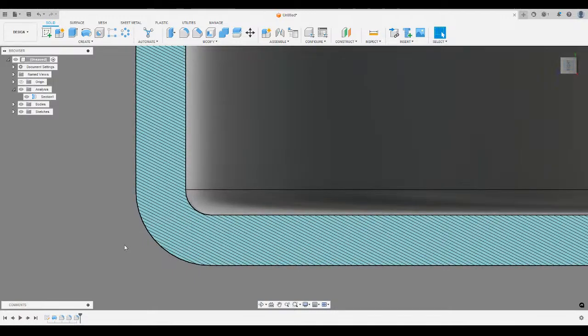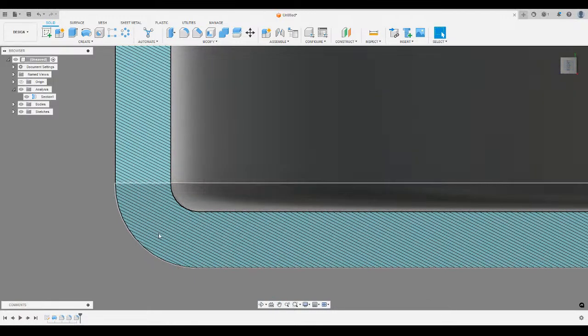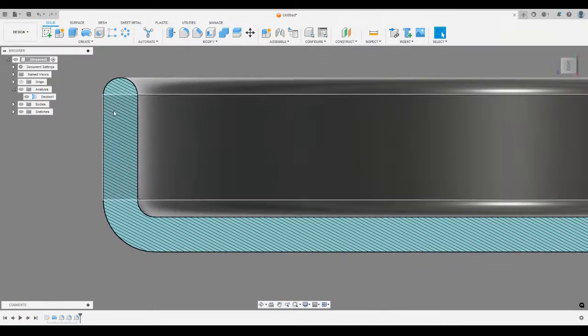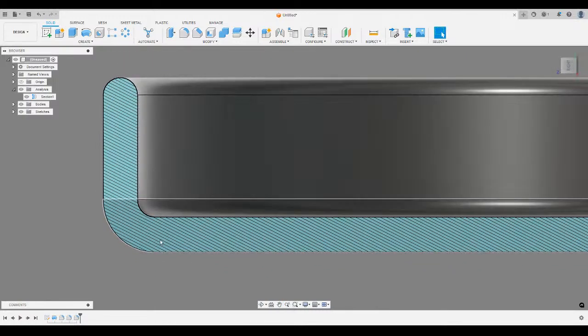And now throughout this entire area, it's 5 millimeters thick. This wall throughout this whole curve is 5 millimeters thick. So now the wall thickness and the bottom thickness, the entire wall thickness of my part, is all the same. So there's not any singular point in here where stresses are going to accumulate.